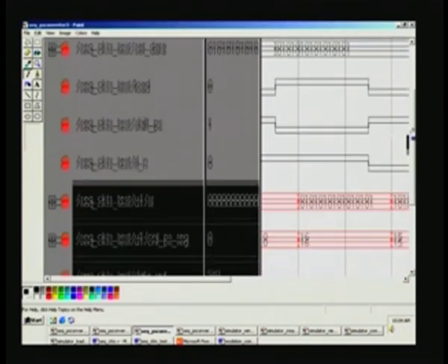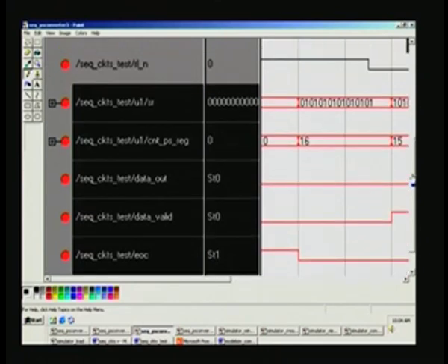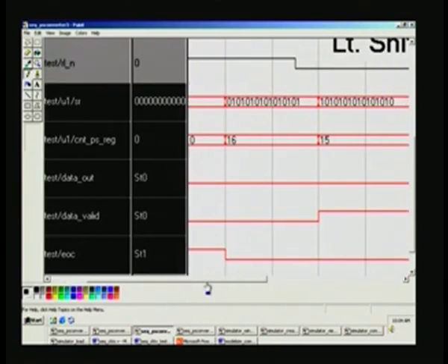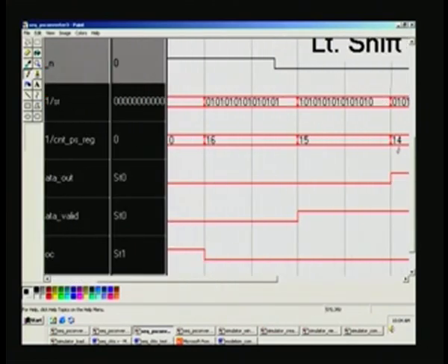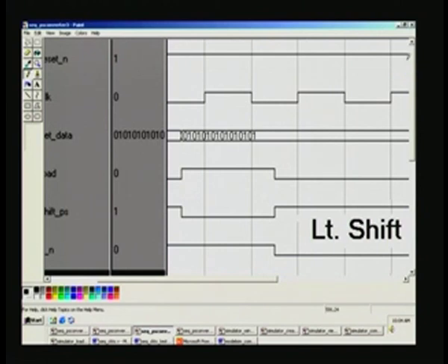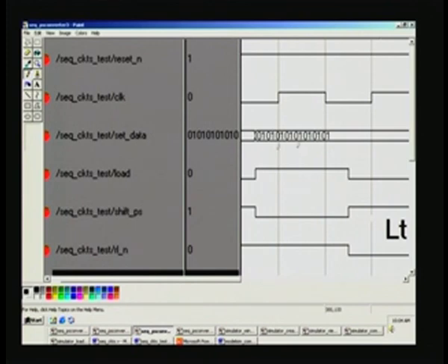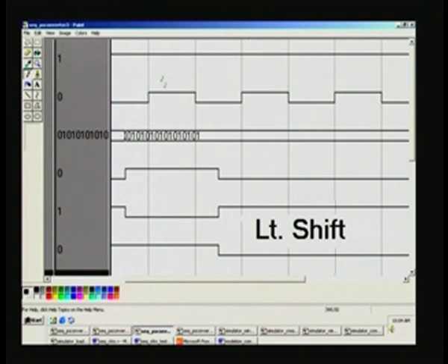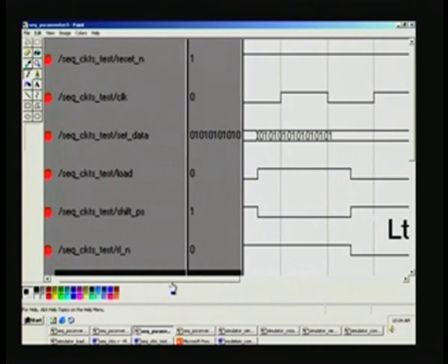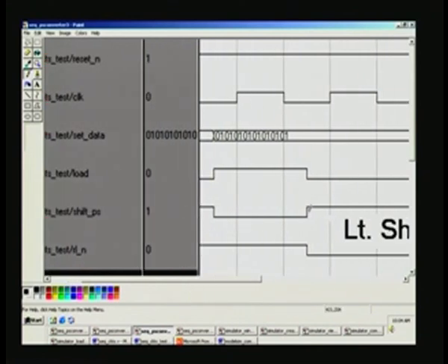straight away we will go into the waveforms of interest, and this is once again shift register here. Before this I will just show where the loading is. Now, this time we are not loading, this is data loaded, you can see set data, and what we load now is 0 1 0, just opposite of the previous content, and this is the load asserted, and shift starts being active right from here the moment it is loaded. So, shift register must start with this value to start.